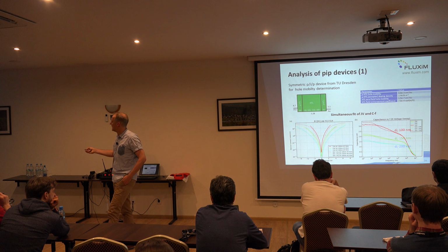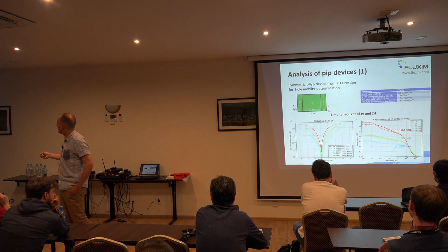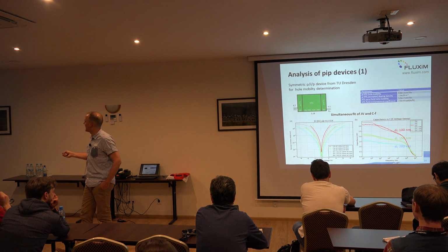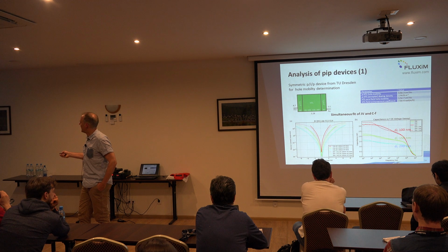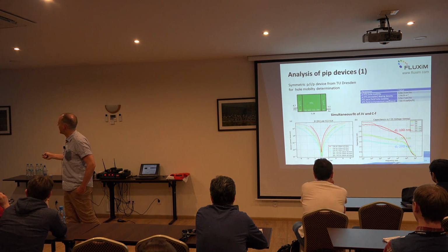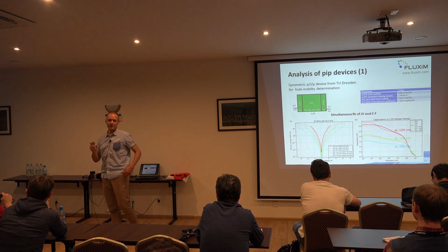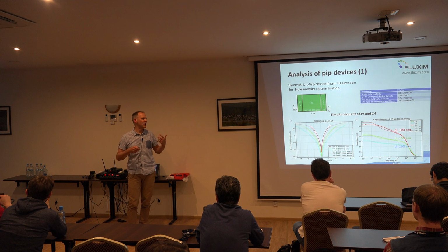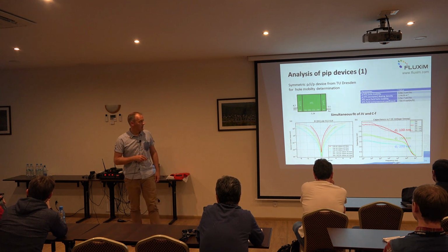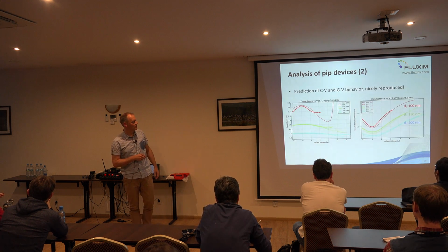So here are the key parameters for this device. We have for the HTL layer a zero field mobility and the field enhancement coefficient. And then for the p-doped layers we have doping density and also a hole mobility in the p-doped layers. There we have high carrier density, so there we can allow for a different mobility of the holes. And okay, that's the fit, how it can look like.